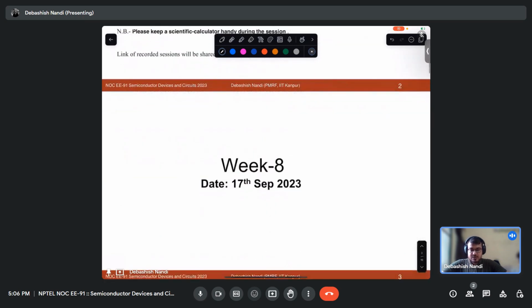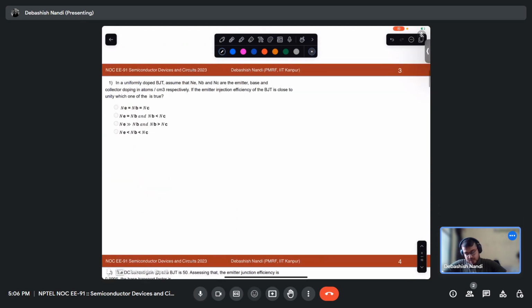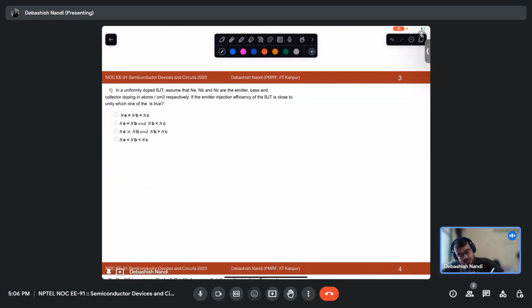Okay, let's begin. This is week 8. Today we'll discuss BJTs, mostly BJTs, and if time permits, we'll discuss the MOS capacitor also. In this question, it is asked: in a uniformly doped BJT, assume that Ne, Nb, and Nc are the emitter, base, and collector doping in atoms per centimeter cube respectively. If the emitter injection efficiency of the BJT is close to unity, which one of the following is true?